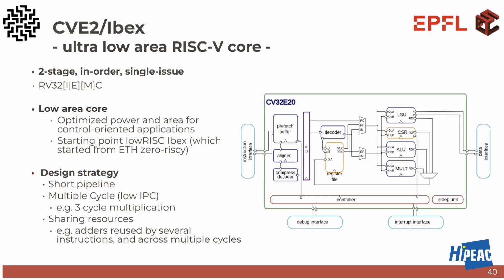There's a prefetch buffer. Do you know, guys, why there's a prefetch buffer on a CPU? If there's only one memory, you can only do one memory access per cycle. So if you have a prefetch buffer, you can actually do a load and not have to stall for the next instruction fetch. Yeah, it's not just the stall, it's to mitigate in case the pipeline stages in front of you are stalling, rather than the memory itself.